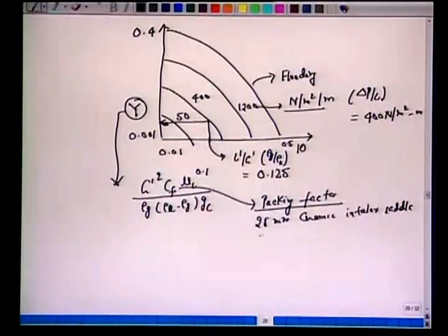So if you look at one of those tables, you will see the type of the packings, the size of the packings, and you will see a factor A, the interfacial area, as well as a quantity Cf, which is a packing factor given by the manufacturer. So take this factor, which would be 98 from the table, and calculate this quantity. If you look at this graph, from this graph, this quantity would be 0.061.